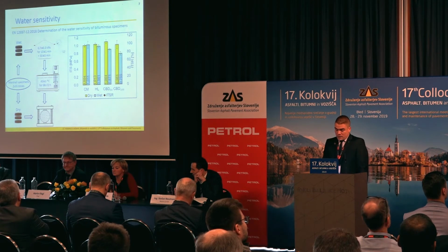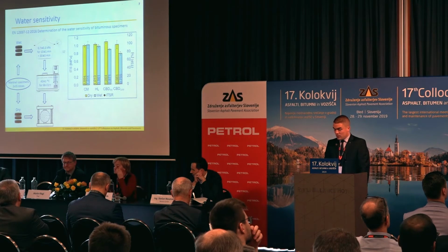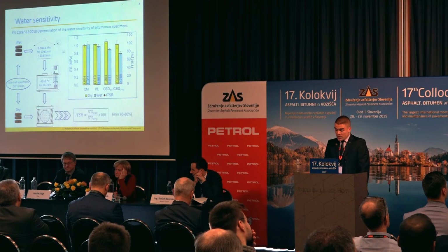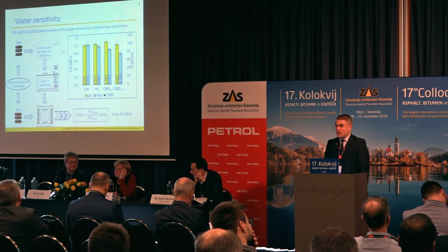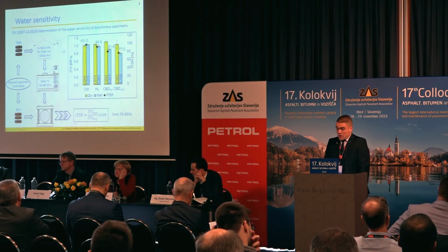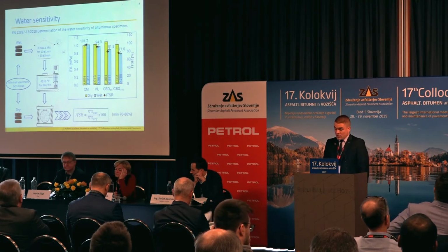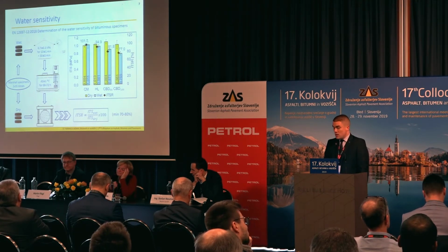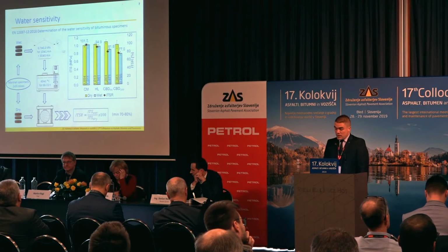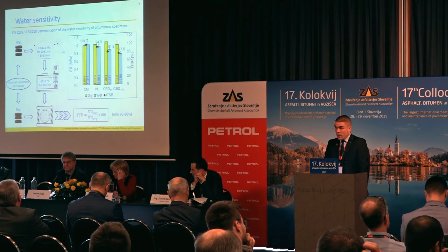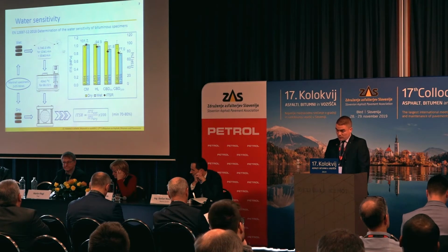their ITS were also measured. It can be seen that water brought a decrease of ITS, but the measure of water sensitivity is actually the ratio between wet and dry subsets of samples. Typically, this ratio depends on the technical requirements, but it goes from 70 to 80%. So all of these mixtures, except the mixture with 100% of cement bypass dust, had a satisfactory ITS ratio.